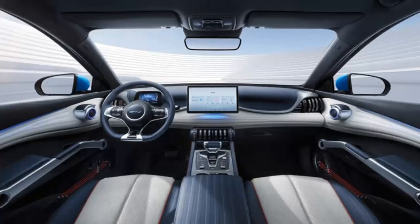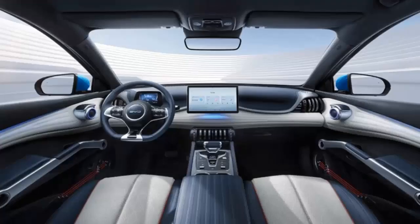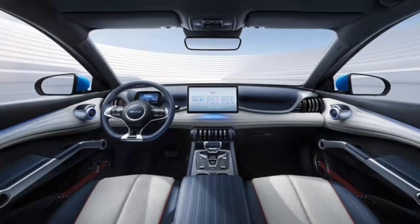The third failure, associated with a bad odor when turning on the air conditioning, may be due to a dirty cabin pollen filter. The following actions are recommended. Change the filter at the appropriate time, and in case of persistent bad odor, clean the ducts with antibacterial spray or foam.